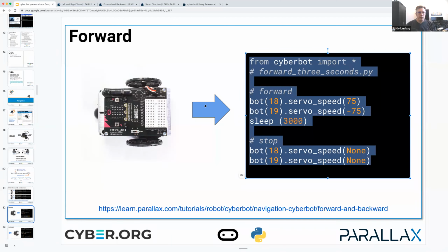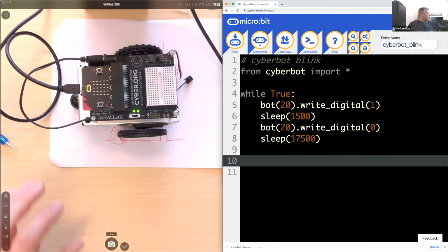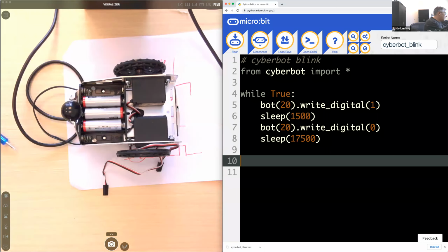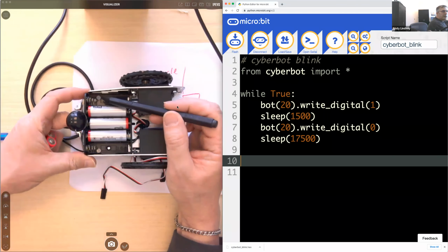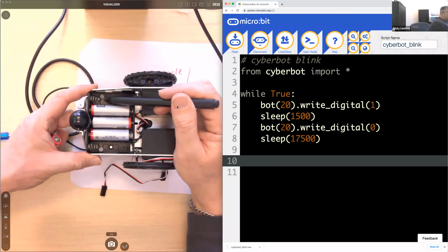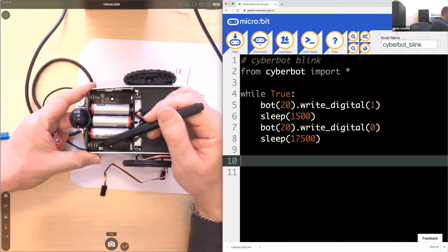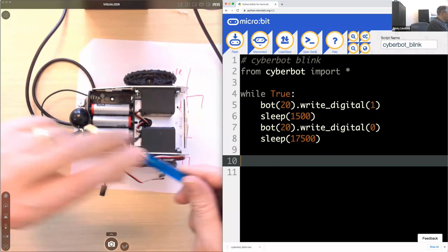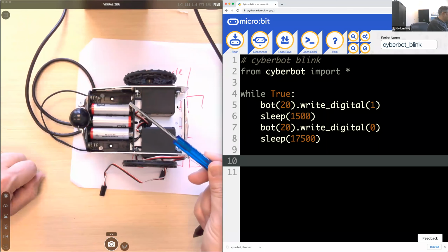And one more thing that I want to just take a side trip and check with you all on is to make sure that you're using the nylon screws. See the white nylon screws here? These white nylon screws are what you want to use to hold the battery pack in place. If you have another kind of screw there, I'd recommend removing it and putting in the white nylon screws using the standard blade on the Parallax screwdriver.